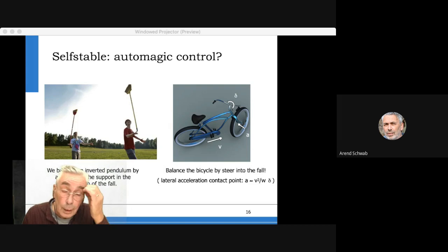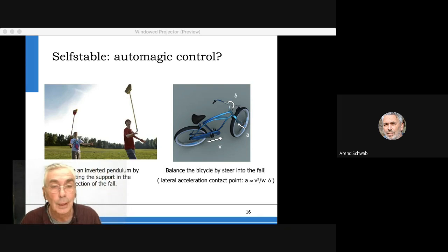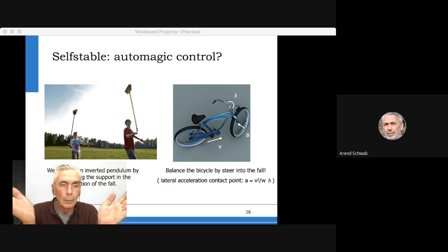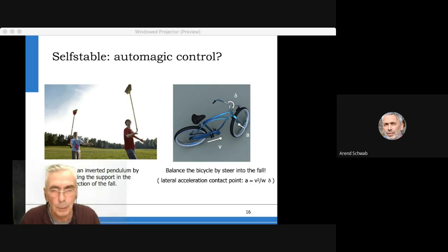However, if you now steer briefly to the left, your bike will fall over to the right because your contact points go on, and you're in a leaned configuration and you go around the corner. And I really encourage you to do it yourself. So ride on your bike with your open hands, push against the handlebar a little bit with your right hand, and you will see the bike steers to the left briefly, and then it will go to the right. Just do the experiment. That's the best proof.